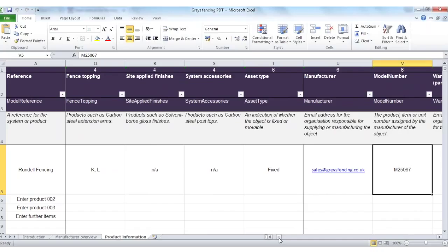Okay, so obviously we've got product data templates. Better still, you could create National BIM Library objects which handle both the level of detail and the level of information. And that National BIM Library object information is back-to-back with BIM Toolkit, so the architect gets all the LOD and LOI plus some COBie Stage 6 information. As a manufacturer, in creating these National BIM Library objects, you're recognising that an architect needs to draw these things and needs to be able to 3D model them and providing them with the detail they need to do so.